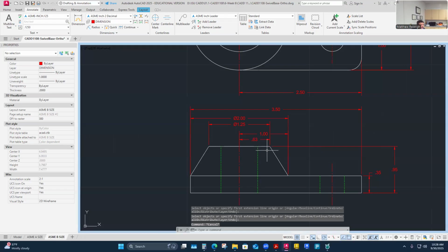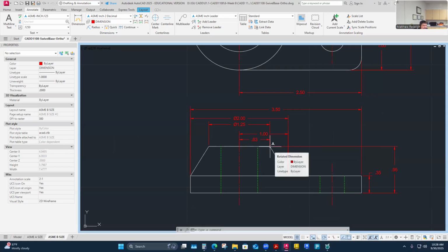I would read something like this as saying from center, that's this really hard control point, my top diameter, I come over 0.63, and then I have this diameter. So I would read this from there, it's there, and then from there it's this diameter. It's almost like this little zigzag that I build if I'm reading the dimensions that way from a control point. And the same way with the outer one, it's 1 inch over from the center line, and then from there, it's 2 inches back the other direction. So it's controlling its location in some ways.